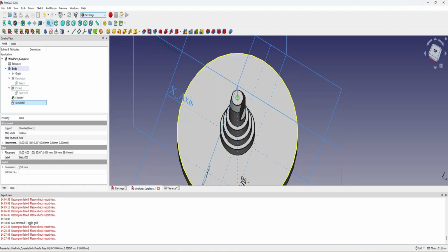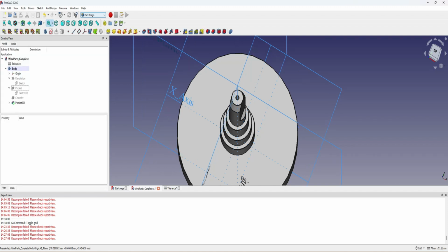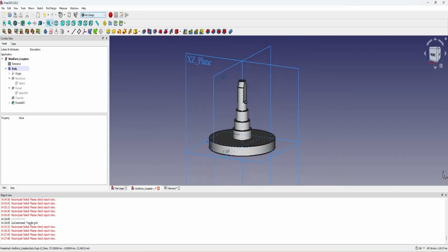Now we can see that the hole is the correct size now. It's actually within the end circle, so I just use the tool to punch a hole through. I don't use the hole tool, I actually use the regular pocket tool to just go through. If I use the hole tool, I have to set all the other dimensions for screw size and all that kind of stuff. I don't really want to deal with that, I just want to go in so many millimeters of the part.